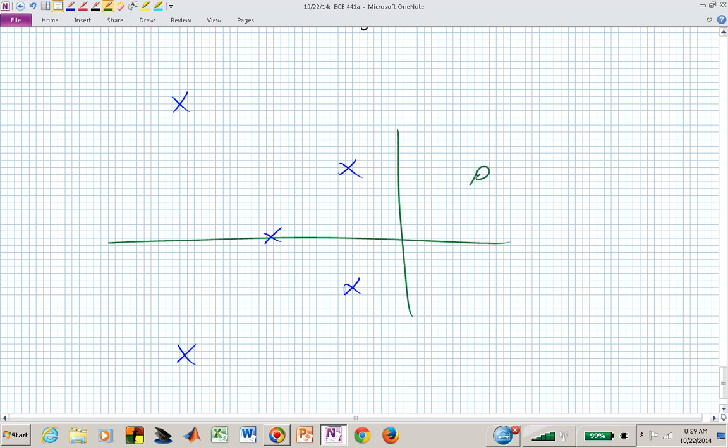Here is our S-plane for a fifth order system. Which of those poles dominate? Which poles will dominate our response? Closest to the imaginary axis, isn't it? The ones that have the smallest real part. And if they're pretty close, they're all going to sort of play together.